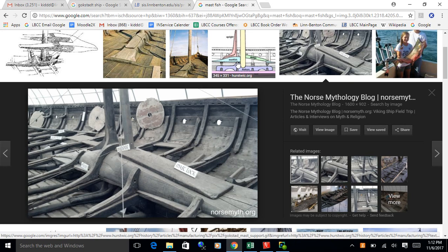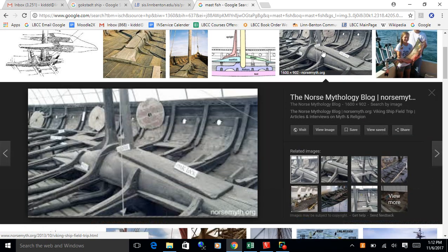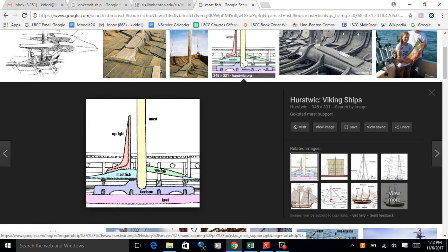And this is probably a good example of one of those things when you're in industry where you're going to have to kind of scratch your head and figure out what to do. I mean, how the heck do you model that? I mean, you could start looking at different loads that this might introduce there to the bottom of the mast, but probably what I'd do is model it both ways, and use the pin joint approach or the ball and socket approach to design the cables, because that puts the maximum load on the cables, and then maybe design it like a fixed support too, and look at the moments that are building up in the mast itself.